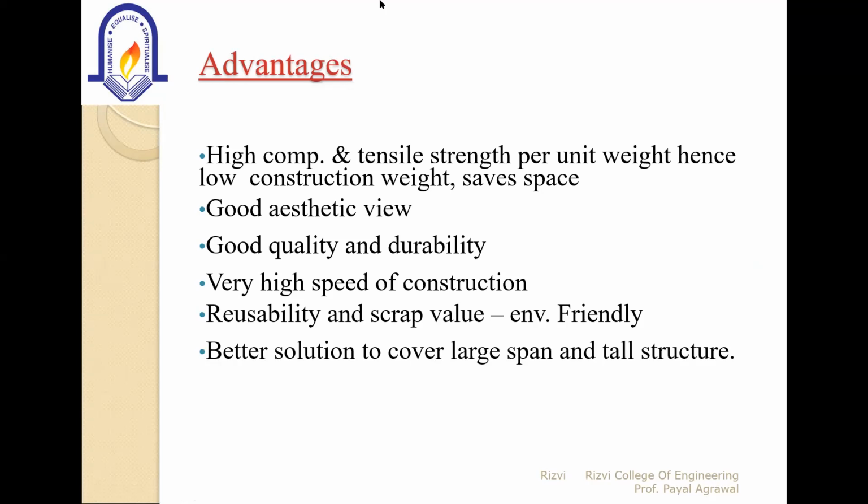As the strength per unit weight is high, it will save your construction weight, meaning whatever your construction weight would be will be saved because of the high tensile strength per unit weight, as well as good aesthetic view if the structure is made up of steel, good quality and durability, high speed of construction, reusability and the scrap value.